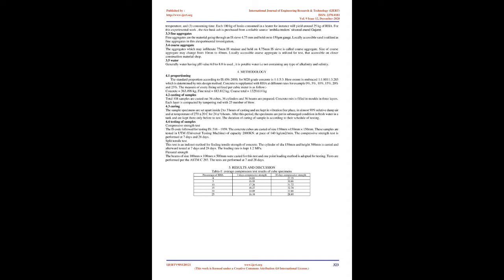2. Objective of research. To examine the beneficial use of industrial waste as a cement substitute in construction work. To evaluate the optimum proportion of rice husk ash as a beneficial replacement of cement in cement concrete. 3. Materials used. 3.1 Cement. For this research work, PCC cement of Ultratech Cement Company is used, that is available in our nearest construction material shop. While adding cement in the concrete mix, it is ensured that the cement is moisture-free and no lumps are found in the cement bag.